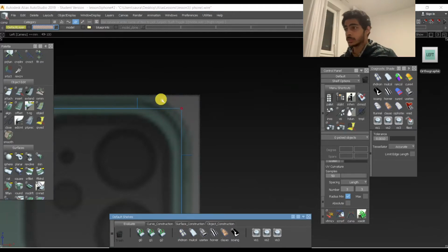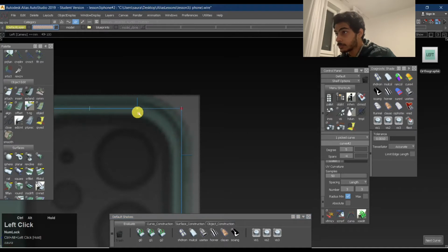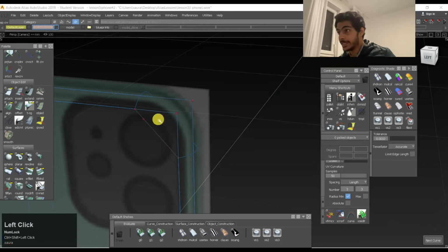What we'll do is, we'll make a curve over here, a 5-degree curve, right? So we'll just snap it across. I told you how to slide objects. It's Control Alt, and if you see, it's sliding over here on this. Control Alt and slide it over here. I have a 5-degree curve over here.